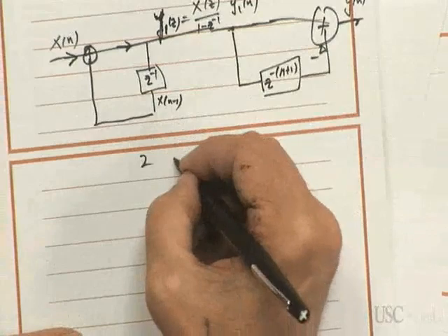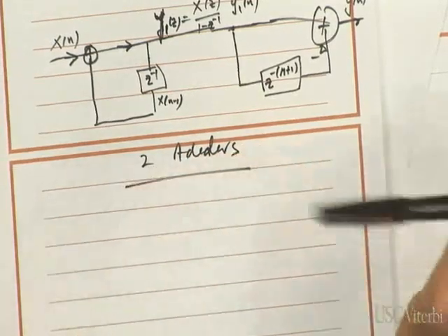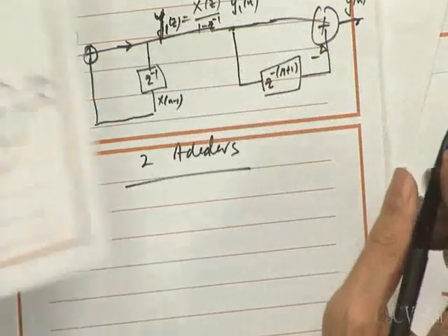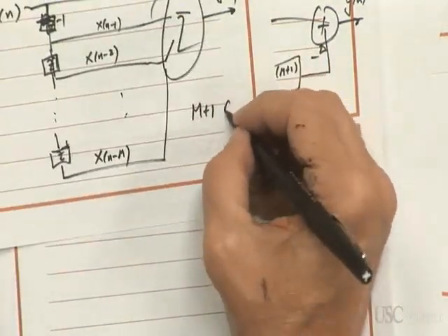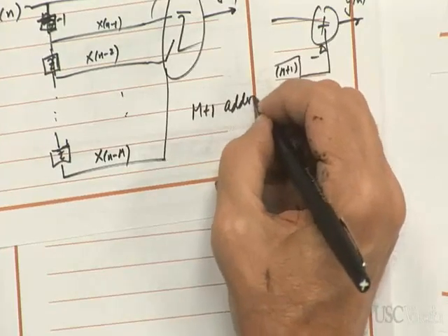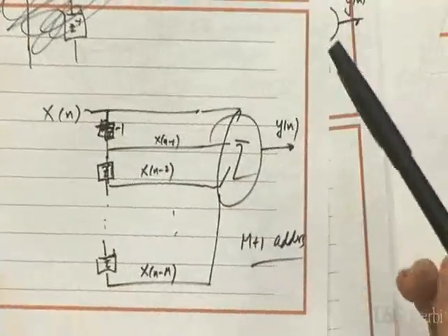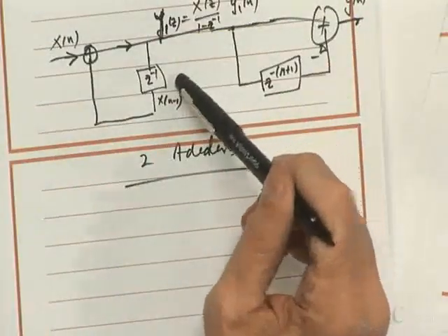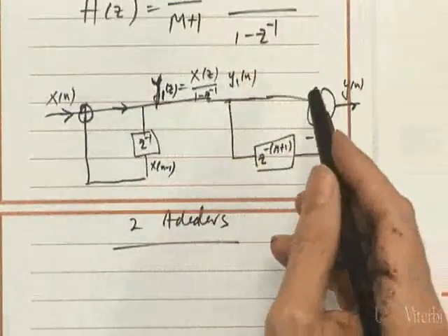So this is done with two adders and some memory, okay, versus m plus 1 adders here. Or I think it's m adders, but who's counting, you know? So here's a case where if we implement this, this actually requires fewer adders.